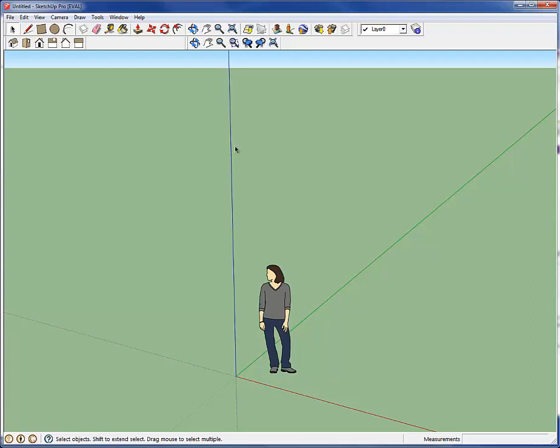So it's important to note. The way that this works, though, from that standpoint of it being a surface modeler, is points lead to lines lead to areas, and then those areas will automatically be enclosed to create surfaces. So that's something that you guys want to pay attention to.